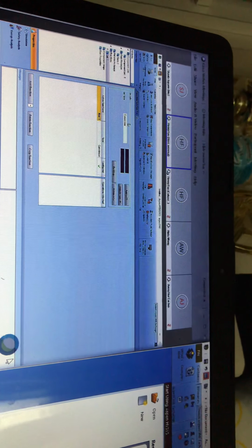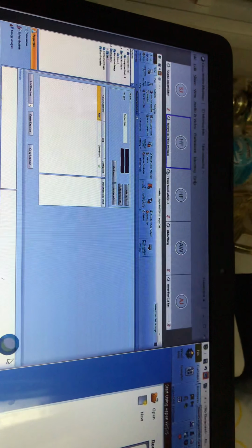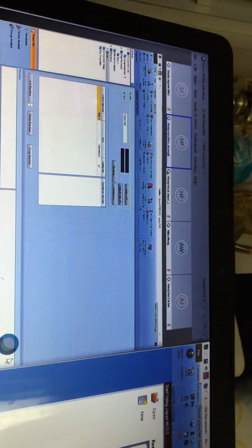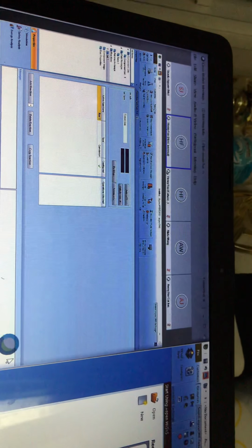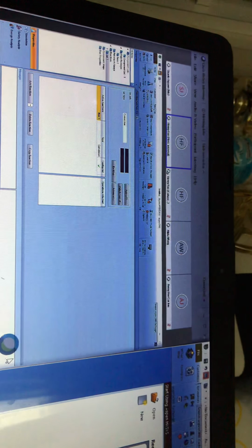Of course, you can still stick with the Methods Assistant. It's an easier way. It's good to know how the Methods Assistant helps you make your decisions. So we have to identify the features of Peng-Robinson, the features of NRTL, and maybe the features of SRK.